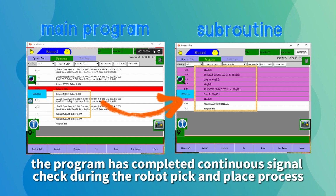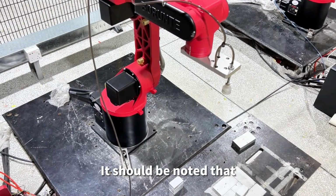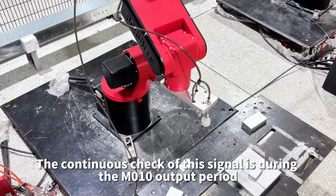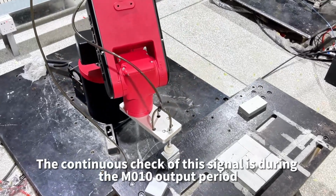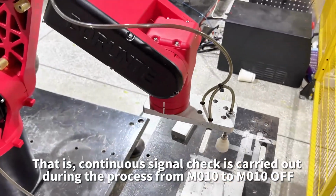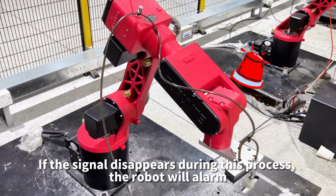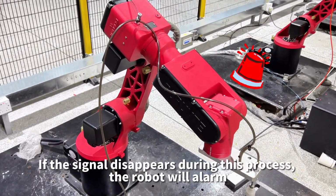The program has completed continuous signal check during the robot pick and place process. It should be noted that the continuous check of this signal is during the M010 output period. That is, continuous signal check is carried out during the process from M010 ON to M010 OFF. If the signal disappears during this process, the robot will alarm.